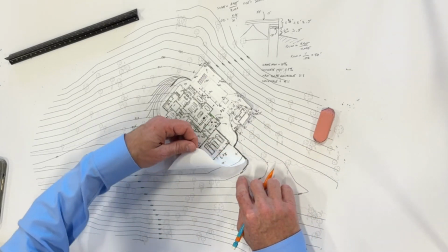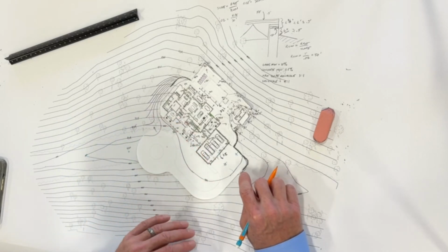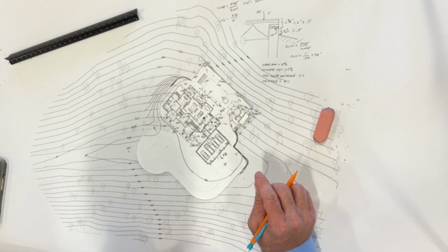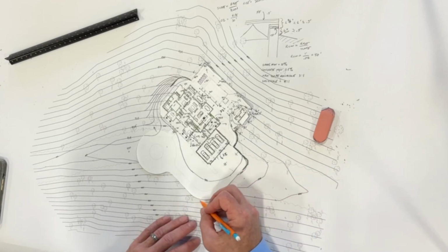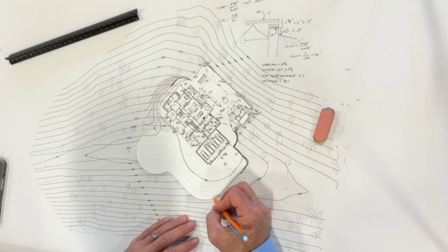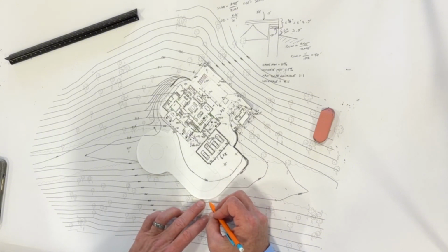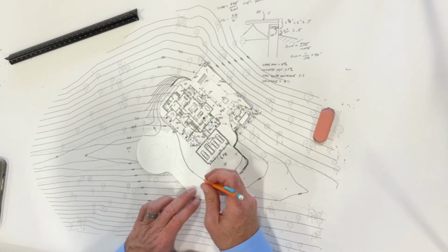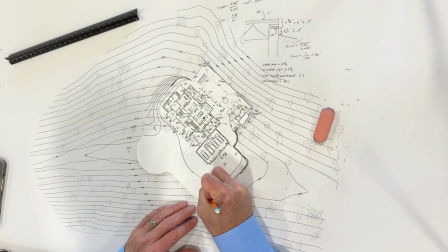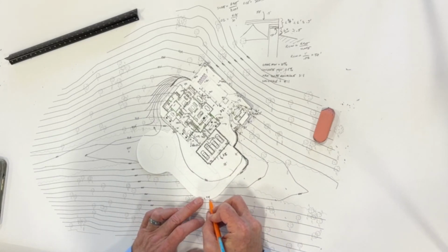Okay, and this is a 936 down here. So we're still, okay, this driveway swings this far over. That's going to be tough, right? Because that's like a 7 foot. If this was a 939 even right here, that would mean this would be a 7 foot high retaining wall here. So we're kind of getting to the point where we're getting like a ridiculous amount of retaining walls, right?